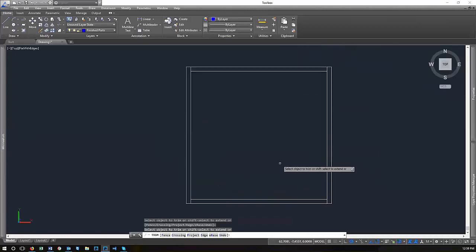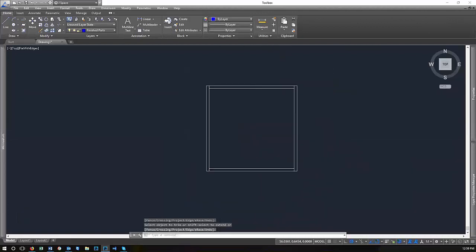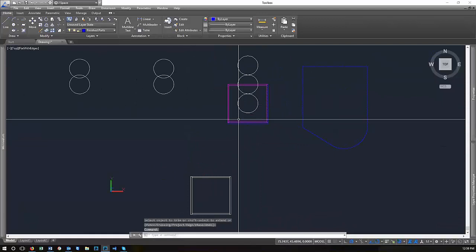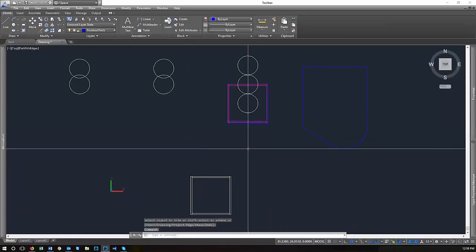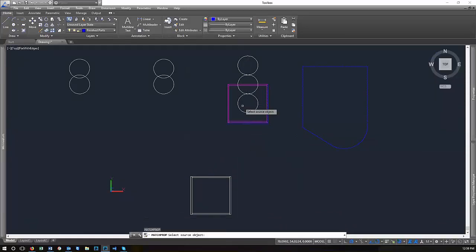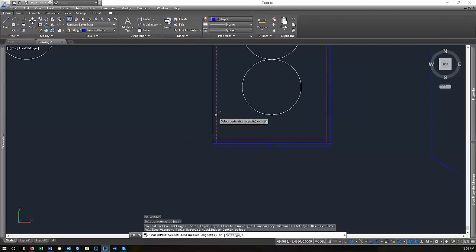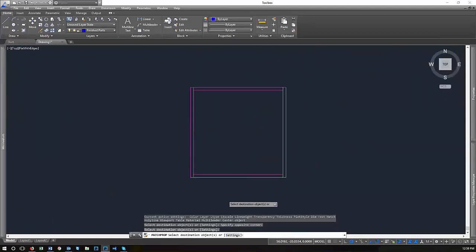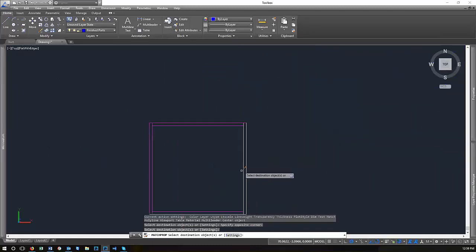So, helpful pro tip, you can hold Shift and it switches from a trim to an extend, or from an extend to a trim. And you can easily do the same thing and faster than clicking and dragging those things out. So now let's use the match properties command to match these properties. That's the internal line there, and one more.